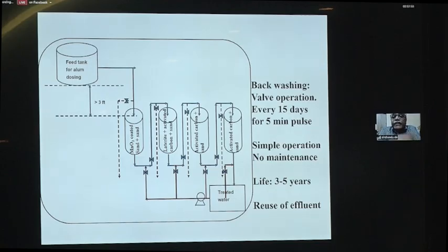Now, every 15 days, there is a backwashing facility here. We have to give a 5-minute pulse, and the filter beds are regenerated. It's a very simple operation. No maintenance is required except this backwashing. It has a guaranteed life of 3 to 5 years, and then we can reuse the effluent water either for recharging the groundwater or reusing in the plant itself.